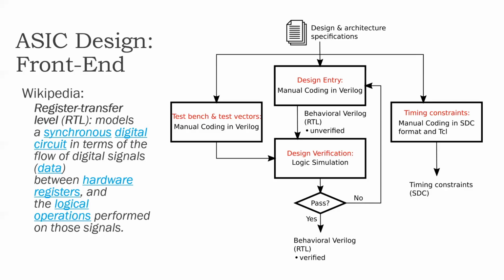So initially, you write some code and then you get behavioral Verilog. It is often referred to as RTL, and RTL stands for register transfer level. On the left-hand side here, I have the Wikipedia definition of RTL. RTL models a synchronous digital circuit in terms of flow of data signals between registers and the logical operations performed